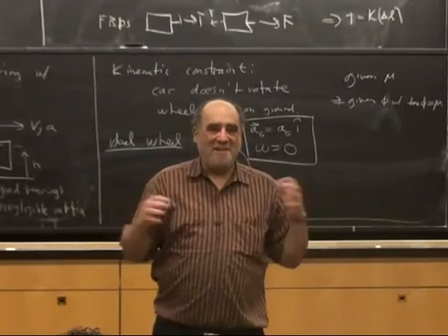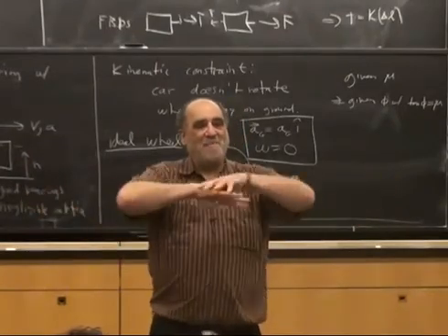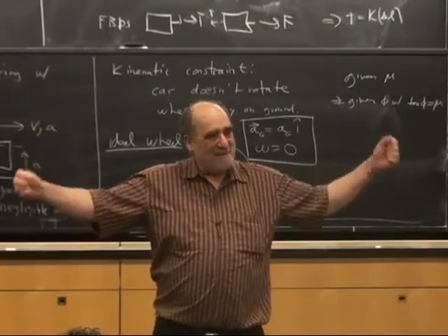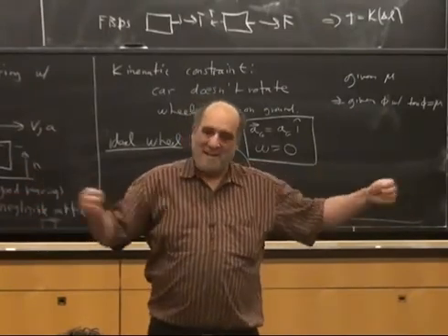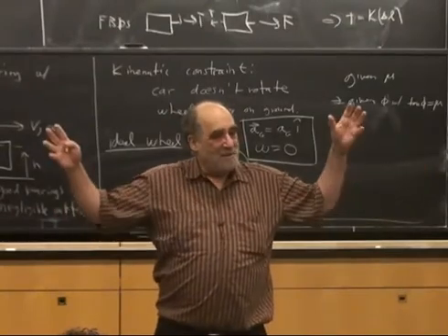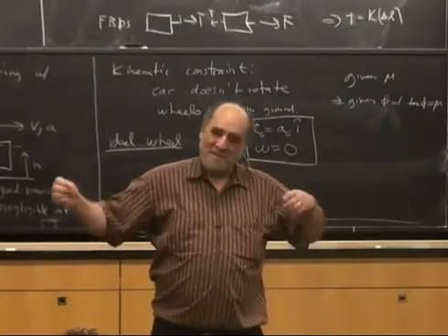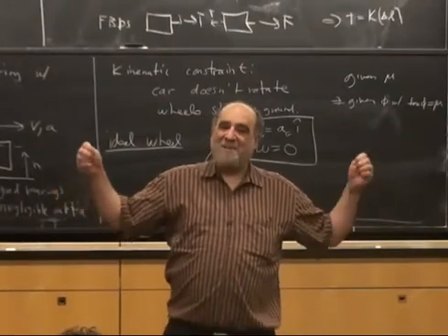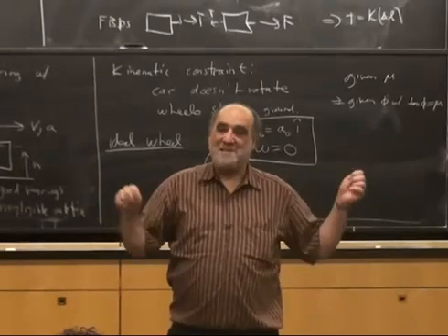I could work around it. I could find a trick to avoid that by using linear momentum balance of the whole system and saying that the whole system had a mass of 2m. Never mind that string. All the parts are moving together. The force is the total mass, 2m, times the acceleration of the system.